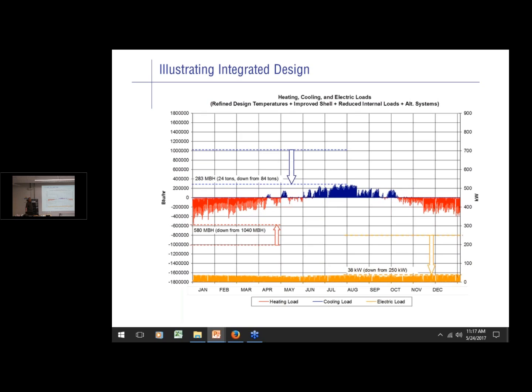Why would that be? Think about conventional systems. This is a little loads piece that I always like to, between these two slides. Conventional HVAC systems impose loads on themselves. It's one of the reasons why certain codes, like the Washington State Energy Code now, are regulating the DOAS systems, and zone level heating and cooling is now a code requirement. They're getting rid of these integrated central systems that have inherent amounts of simultaneous heating and cooling. So you've got overcooling and reheat in VAV, you've got fan heat, you've got the ventilation load that's just coming in without any heat recovery on it.